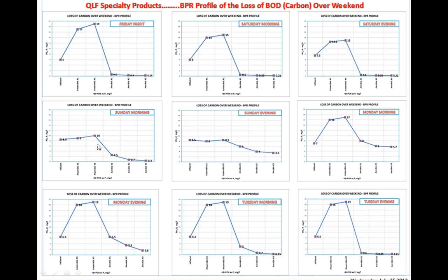And now the uptake. You look here on all of these, the uptake has been just fine, but now the uptake is starting to show signs of stress. And by Sunday evening, it's flatlined, and the uptake has gotten very poor. Now Monday morning, since the organisms, the PAOs, still have phosphorus in them, when they get the carbon load, it jumps this up right away, but they don't have the ability to take that phosphorus back in the aerobic zone. That's what I was talking about as far as a carbon overdose.